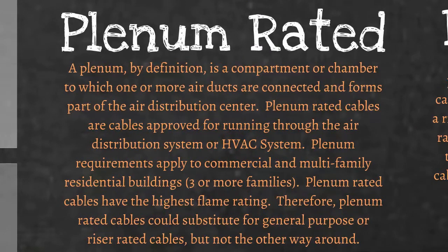Plenum rated cables. A plenum, by definition, is a compartment or chamber to which one or more air ducts are connected and forms part of the air distribution center. Plenum-rated cables are cables approved for running through the air distribution system or HVAC system. Plenum requirements apply to commercial and multifamily residential buildings with 3 or more families. Plenum-rated cables have the highest flame rating. Therefore, plenum-rated cables could substitute for general-purpose or riser-rated cables, but not the other way around.